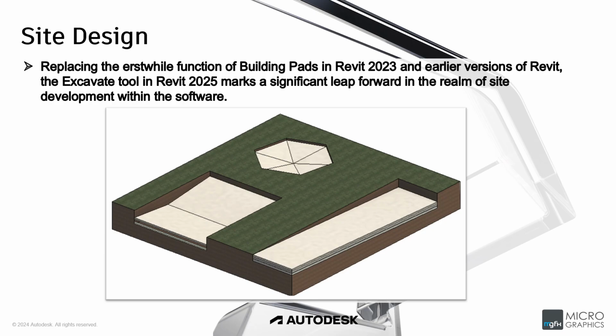This tool is designed to offer enhanced functionality, improved precision, and a more intuitive user experience, empowering architects and designers to create accurate site models with ease, including municipal or local authority submission plans. But it is not limited to the area. Volume calculation is easy with a parameter within the topo solid type properties. One of the standout features of the Excavate tool is the ability to provide precise volume calculations by accurately measuring the volume of soil removed from the topo solid, optimizing material usage and streamlining the construction process.